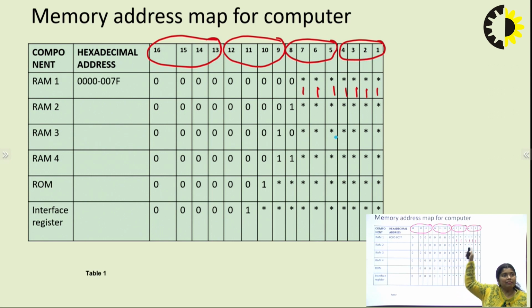Now, when we find the higher order range, in the don't care condition these 7-bit values are considered as 111. In the lower order range, when we find the address, it is 000, and the higher order range has 111. So the zeros stay as 0, the next is 0, then the 111 is 7, and the last 4 bits are all 1, so we treat it as 15, that is F in hexadecimal. So the hexadecimal higher order range will be 007F.